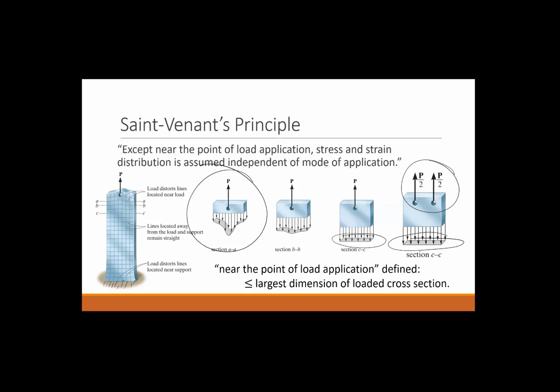We're going to talk a lot about average stress when we do normal stresses, or when we do uniaxial applied loads, we're going to calculate P over A. But I want you to always keep in mind that that's because we're dealing with the central region of this body. We're assuming that we're far enough away from the load application. If you want to know the exact stress in that load application area, that's a more sophisticated question than we cover in this class. And really that's a more important question. Why is that a more important question?